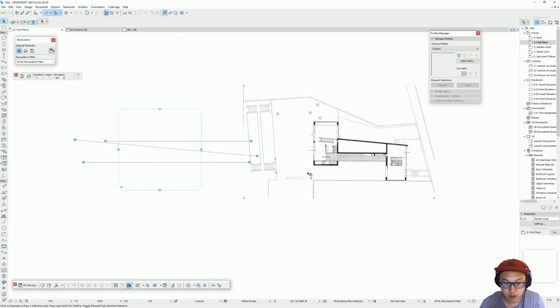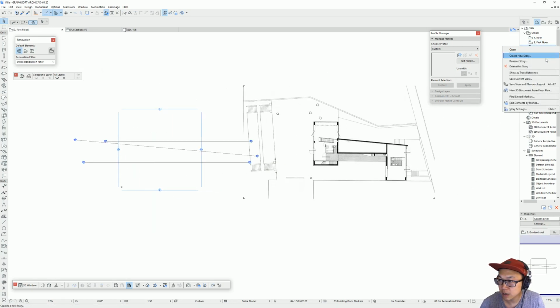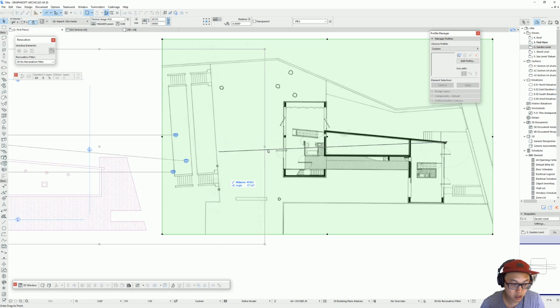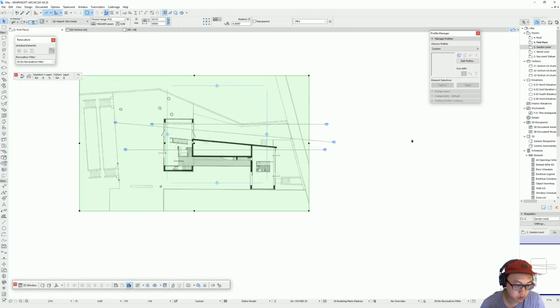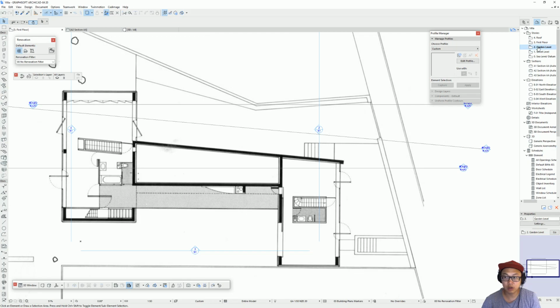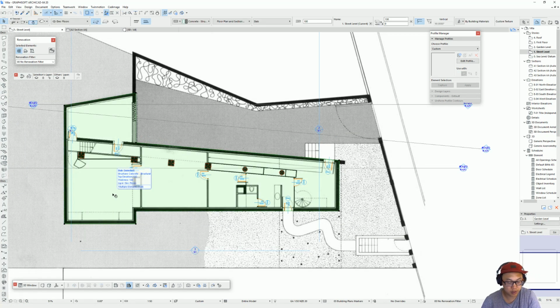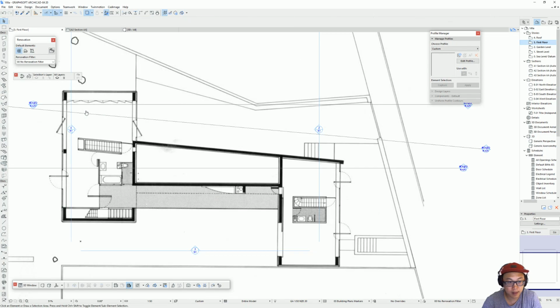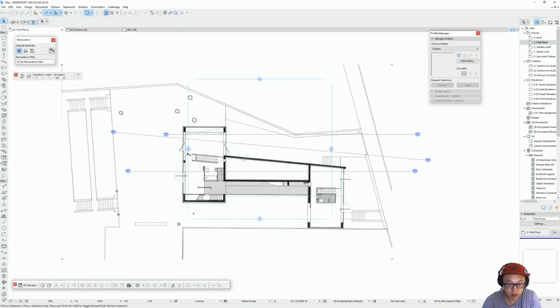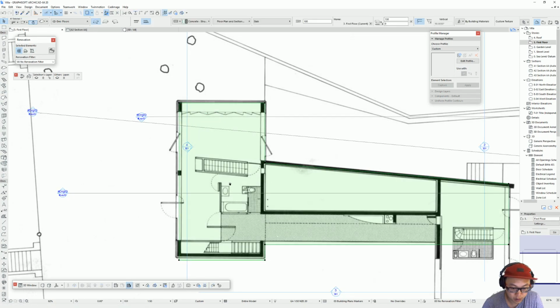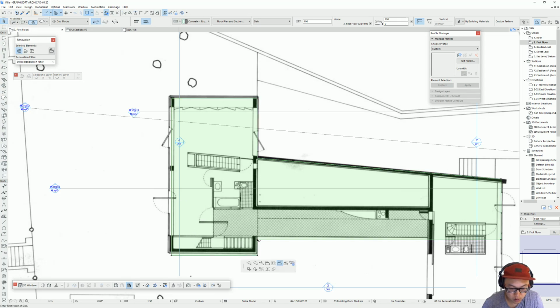Let's go to the upper levels, and here I'm going to show trace reference so I can move this, and I'm going to use that little point as the reference. I'm going to go to gallery level, copy that slab, and actually I'm going to copy the one below because it was already extending a little bit in here, and I'm going to copy, and you can see I'm just going to drag that point, and yeah, size is this 7.5.